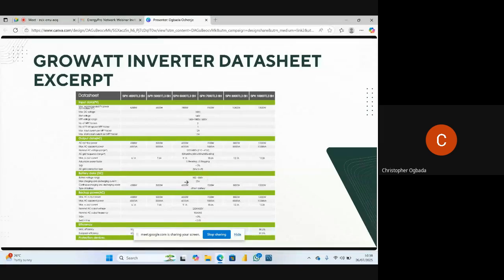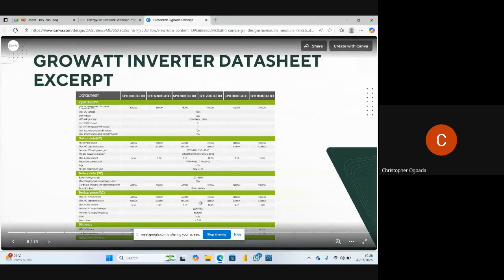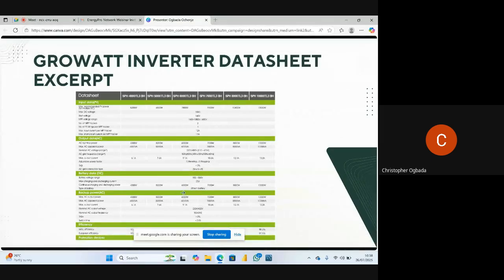So if an inverter's charging current is 25, for example, which is the maximum, and you put in a lithium ion battery where they said the charging current should be around 50, or you put so many lithium ion batteries in parallel, then at night, by the time they put a load on it, it runs down. You say, oh, we have about that many panels on it, you should have charged, but the charging current is low, so the charging is going to be very slow, right? So you may not really get full no matter what you have on it, because the inverter has a limitation.